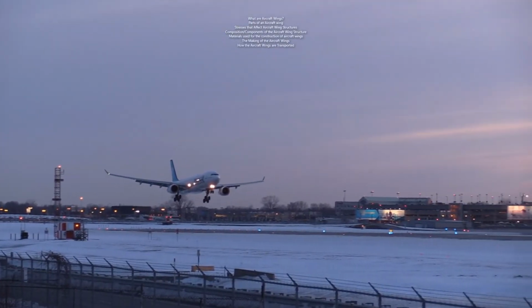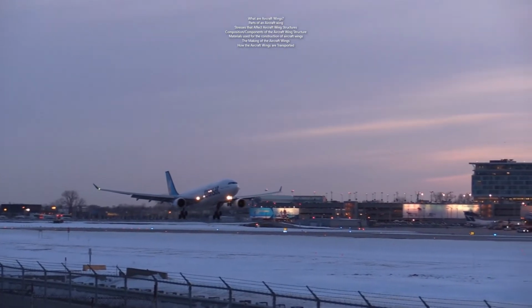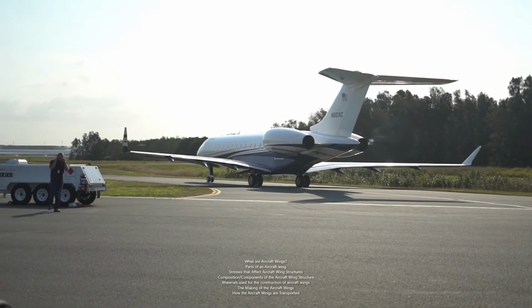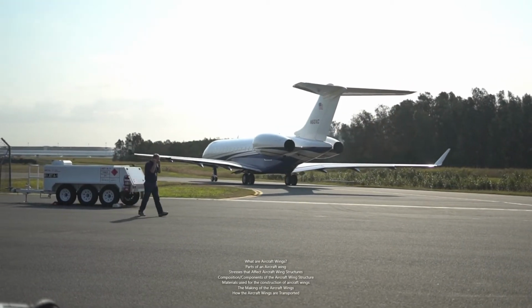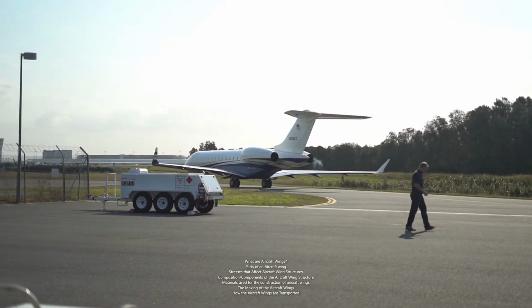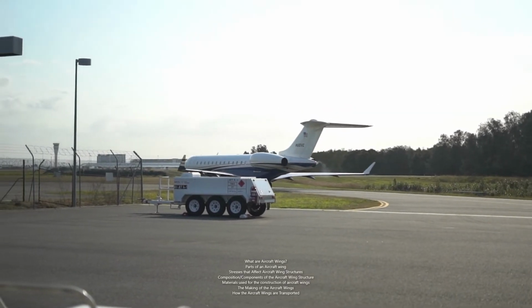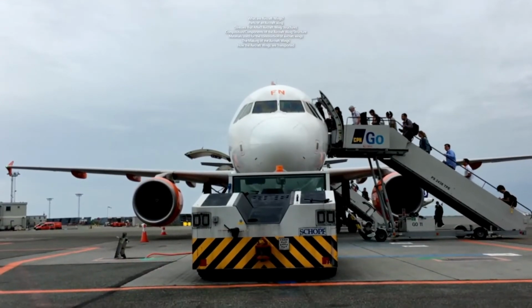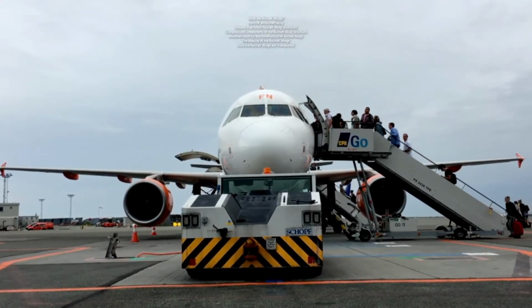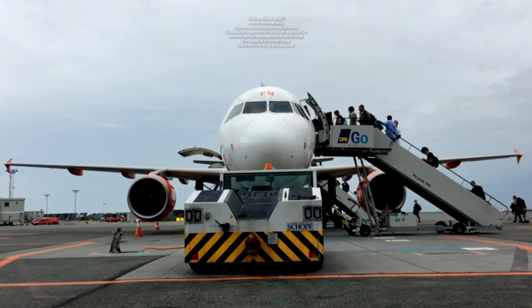Landing gear. Some wings have points at which the landing gear of the aircraft is attached. Otherwise, the landing gear is attached to the fuselage. Flight control surfaces. These are components that help the aircraft change its attitude in the commanded direction. Primary flight control surfaces cause the aircraft to move about its three axes of rotation. The ailerons, which are used to roll, are the only primary flight control surfaces on the wing. There is one of them on either wing.